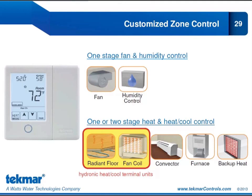We can also operate a fan, and for hydronic heat-cool applications, we can control a radiant floor as our first stage heat, with a fan coil as our second stage of heat in a forced air system. And then when we switch over to cooling mode, we can offer radiant floor cooling with forced air cooling through the fan coil. So a very flexible control. You can see we can also control other types of heat emitters, a convector or furnace, backup heat. But for the hydronic heat-cool applications, we are focusing on the radiant floor and the fan coil.